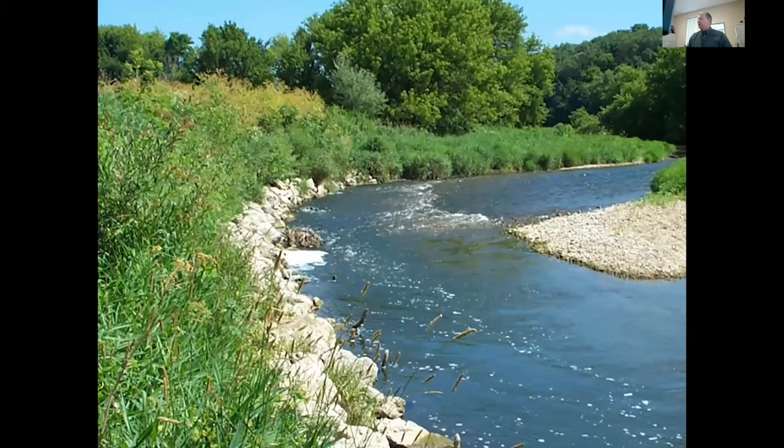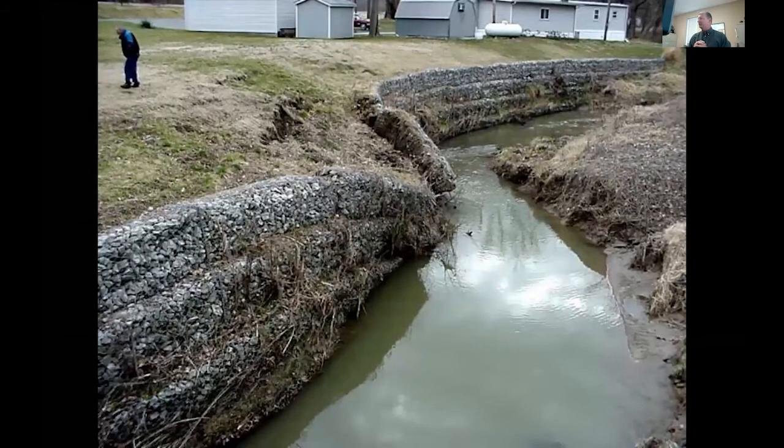So here's an example showing how the velocities can now be concentrated over where this protection is. And that's not necessarily a bad thing. It can add diversity to the channel. It can add this riffle pool sequence to the channel. So as long as your protection is deep enough and you know that it's in the right place, then that's not a problem. Where it is a problem is if you try to use some hard armoring sort of method,